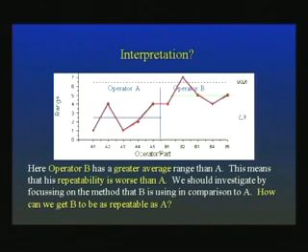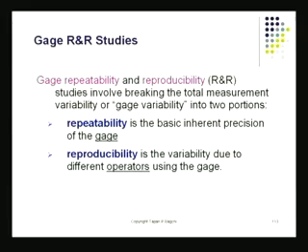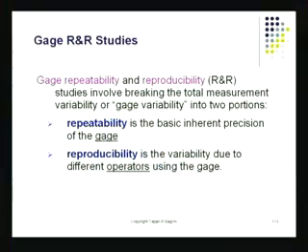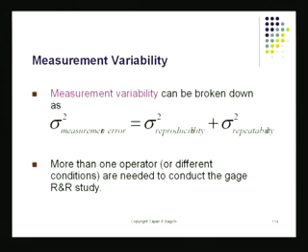For that, you have to do this gauge R&R study, and some special methods are there. I'll just mention this word to you, gauge R&R. Wherever you are, please make sure people have done a gauge R&R study before you go into your TQM application, before you go into your control charts, before you go into your Six Sigma projects. Only then you start your Six Sigma project. This is like taking care of your groundkeeping, basically your housekeeping.